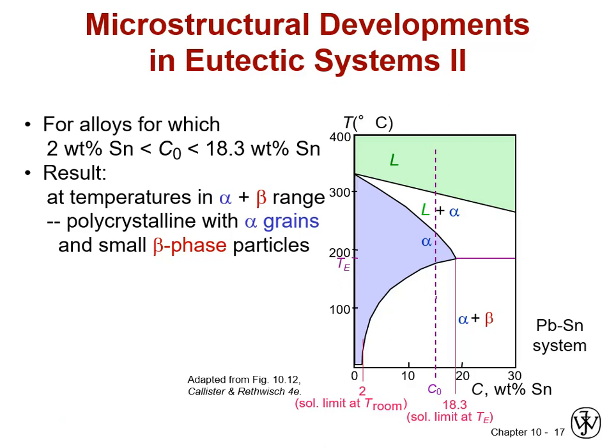And that's very important for a very important strengthening mechanism that we'll look at called precipitation hardening, where we do that on purpose, and then we go back and give a little bit of heat to our material and allow that equilibrium second phase to precipitate, and effectively load the microstructure up with more strain fields and make it very strong without losing much in the way of fracture toughness.